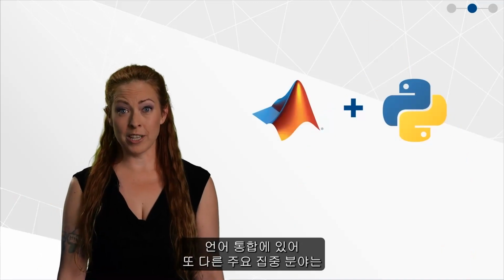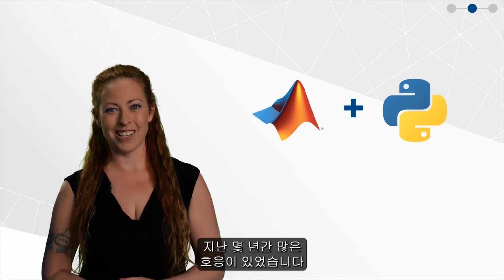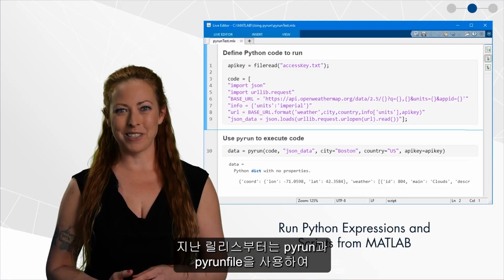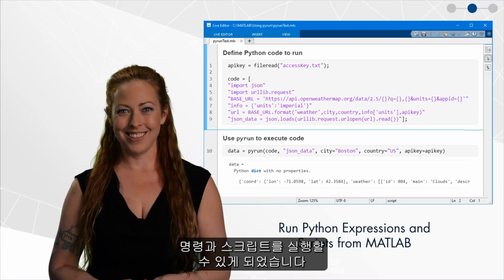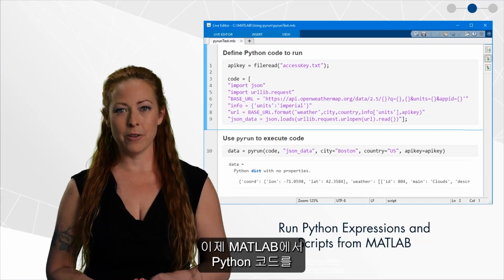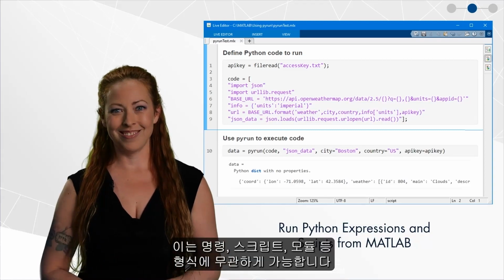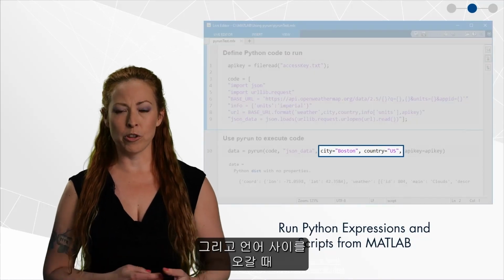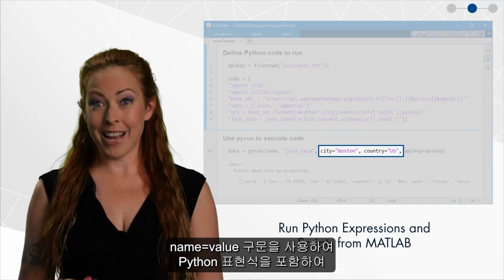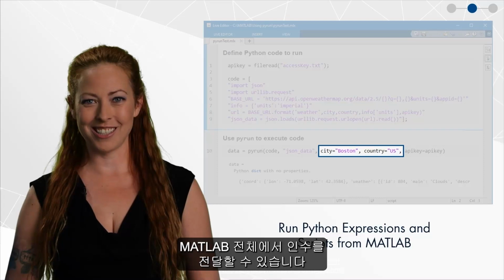Another big area of focus in language integration is using MATLAB with Python. It's gotten a lot of love over the last few years. As of last release, you can run commands and scripts using pyrun and pyrunfile. This just makes it easier to integrate. You can run Python code from MATLAB now, no matter how it's organized, whether it's a bunch of commands, a script, or a module. And when you're going back and forth between the languages, you can use the syntax you're most familiar with. You can use name equal value syntax to pass arguments throughout MATLAB, including in Python expressions.